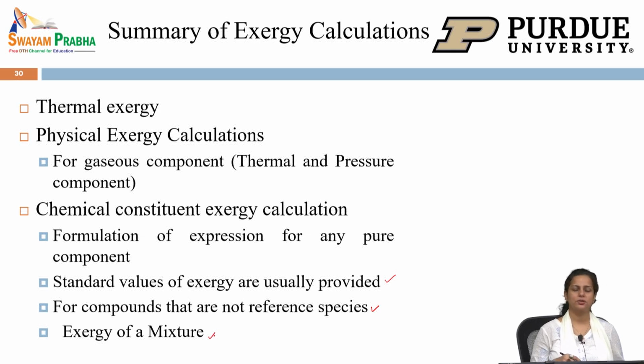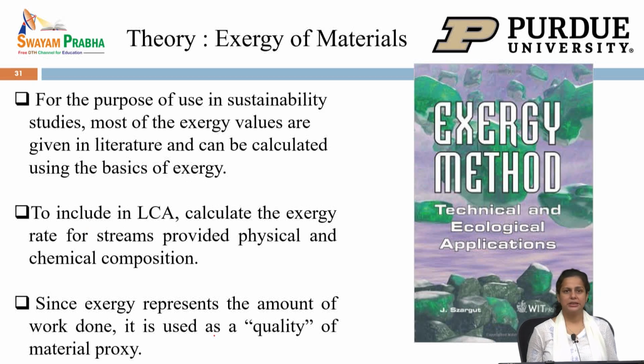And then exergy of a mixture is simply the idea that you are doing some additional work to bring the constituents together. So, you have the part that is the contribution from the molar exergy of the constituent itself plus the part which is the contribution because of the total work done. There is a detailed book on exergy method for technological and ecological applications by Szargut, and that has been a standard book. If you have more interest in actually doing the exergy calculation, you can use this book as a reference. For the purpose of sustainability, most of the exergy values are given, but for materials that we are introducing new at different temperature and pressure, we might want to calculate it.